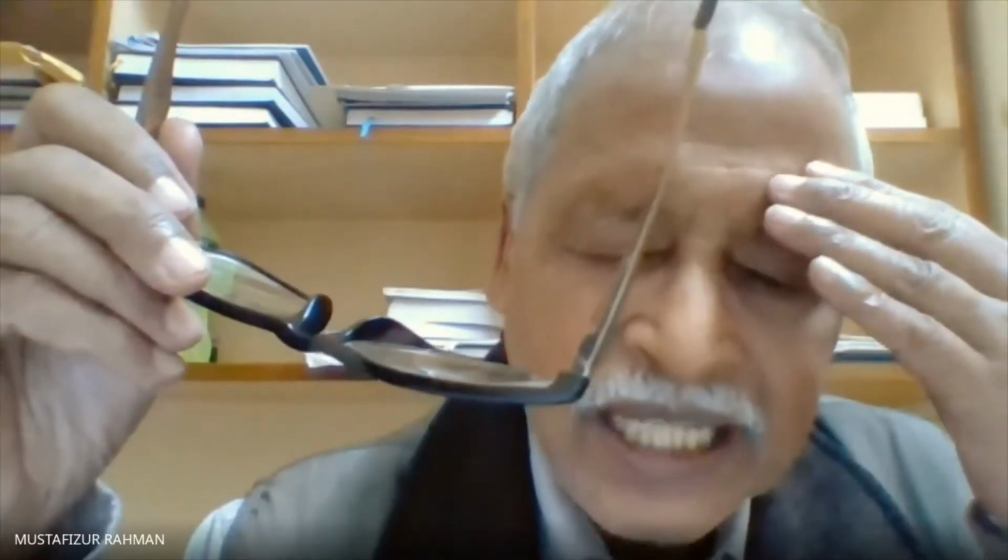Although the slab is supported on all four edges, the effect will go with respect to the shorter span, and only 5% load will be transferred to the longer span. So we had solved the problem. The solution is very simple. Only the first few steps are different. After that, it is exactly similar to whatever we have done with respect to a simply supported beam.